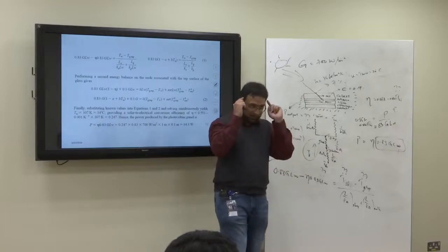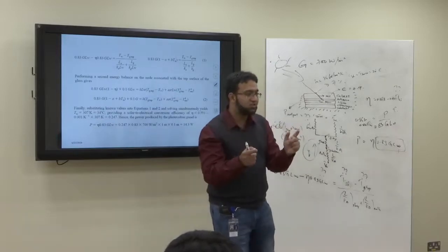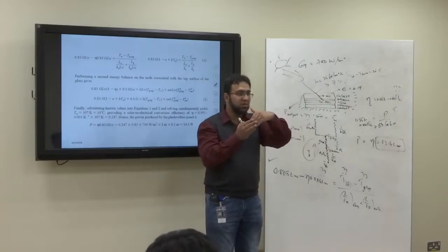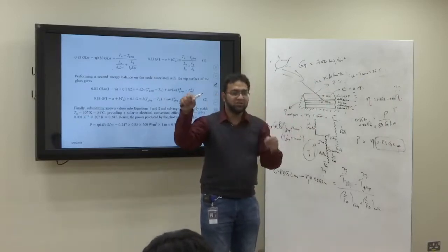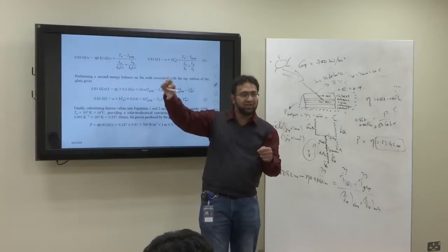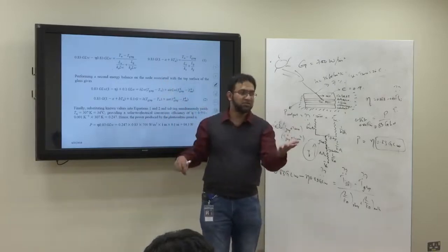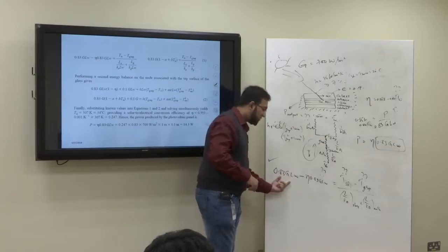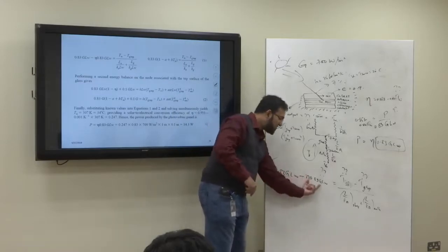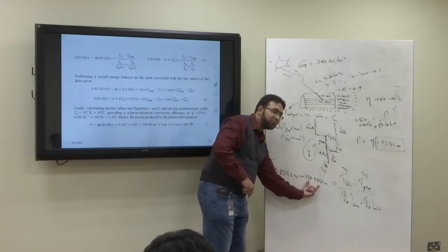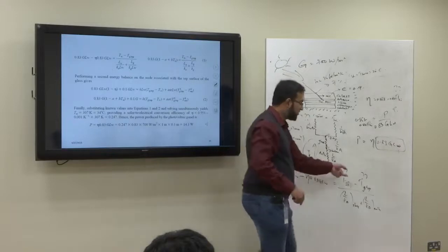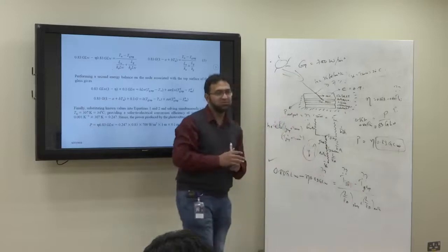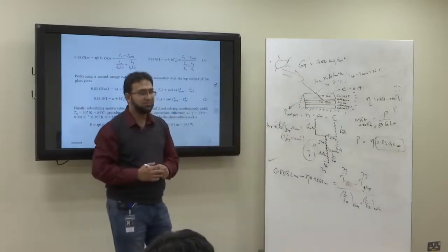For finding out how much is the heat, the logic is that the amount of energy coming onto the silicon layer is converted into electrical energy and heat. So if we subtract the electrical portion, then the remaining is heat. So this is the total energy coming to the silicon layer minus the electrical energy produced, which equals delta T upon the total resistance in between the two. Is it clear?